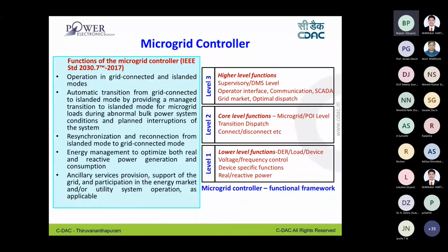And what is a microgrid manager? Basically, a microgrid manager selects the operational modes of the microgrid. This is from IEEE standard 2030.7-2017, the IEEE standard for the microgrid manager. The operation of the microgrid in grid connected or islanded mode is selected by the microgrid manager, and it enables the automatic transition between the different modes, that is grid connected and islanded mode.